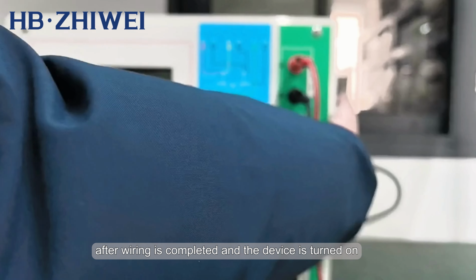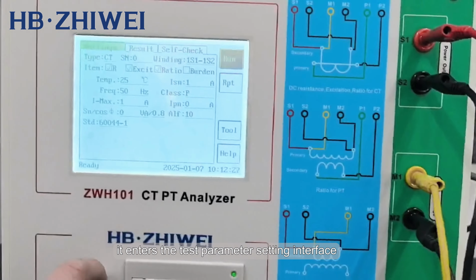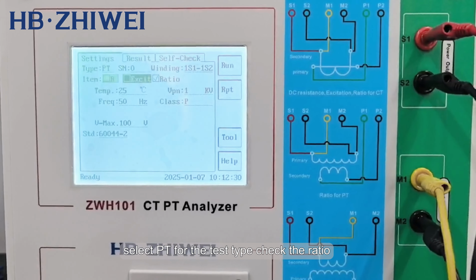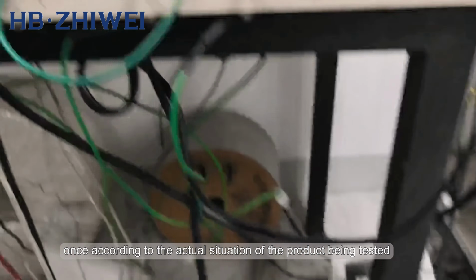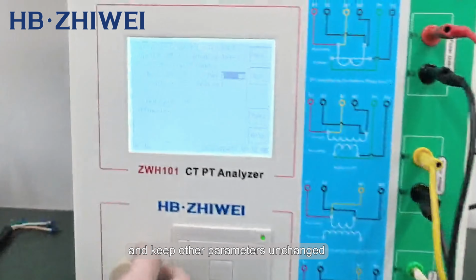After wiring is completed and the device is turned on, it enters the test parameter setting interface. Select PT for the test type, check the ratio. Next, we only need to input the rated voltage once according to the actual situation of the product being tested, and keep other parameters unchanged.